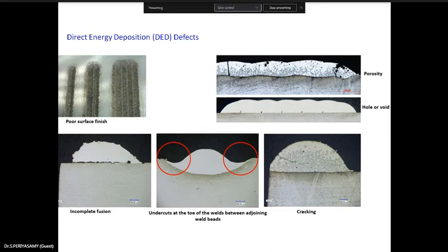So you may have small particles, the size is in the micro range, even some nano. In that case, they will be entrapped within the particular layer. The surrounding will be melted and consolidated, but some particles may be unconsolidated. So in those cases, you have a different behavior in the testing, or wherever you are going to use that particular part. So the next one is porosity.